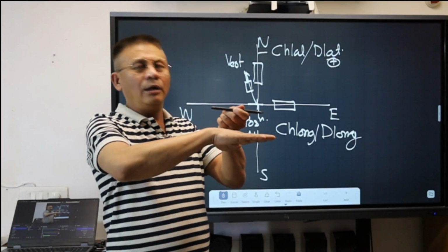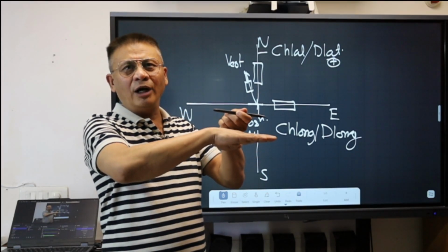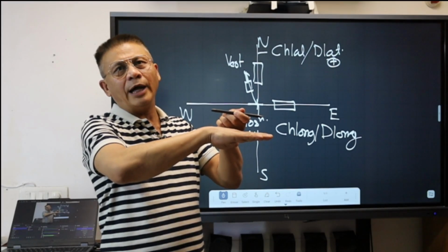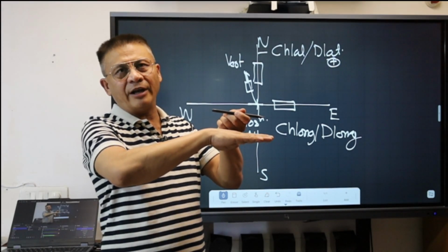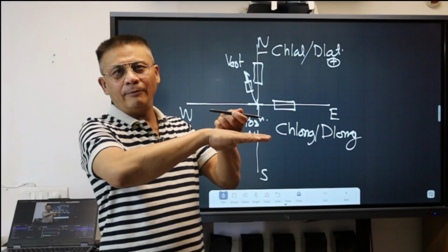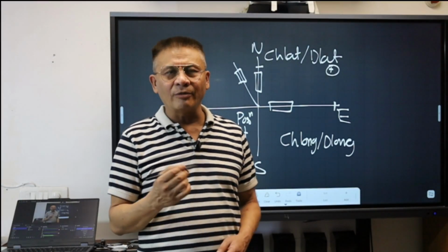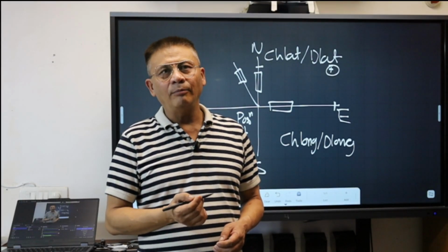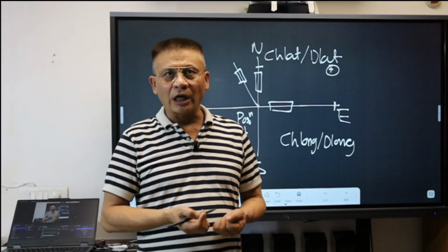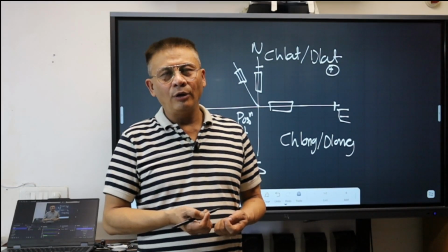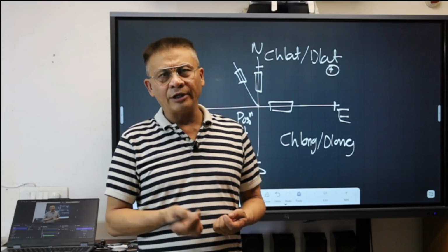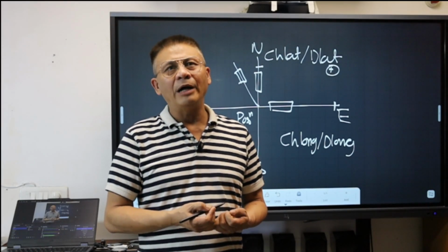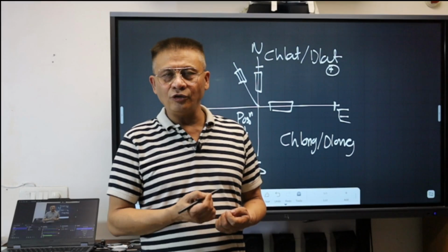So even if the aircraft carries out the maneuver, these gyros will continue aligning in their respective directions which were intended for them. This stabilization of the platform can be done by using the conventional gyro, that is the rate integrating gyro, or by means of a ring laser gyro.